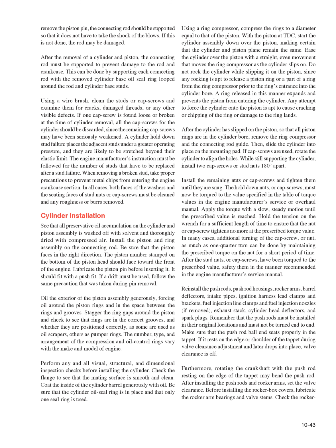In all cases, both faces of the washers and the seating faces of stud nuts or cap screws must be cleaned and any roughness or burrs removed. Cylinder installation: see that all preservative oil accumulation on the cylinder and piston assembly is washed off with solvent and thoroughly dried with compressed air. Install the piston and ring assembly on the connecting rod. Be sure that the piston faces in the right direction. The piston number stamped on the bottom of the piston head should face toward the front of the engine.